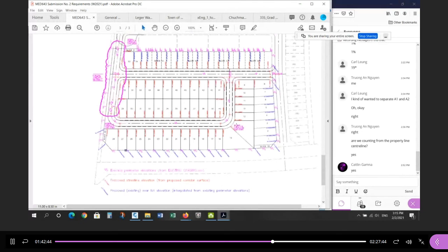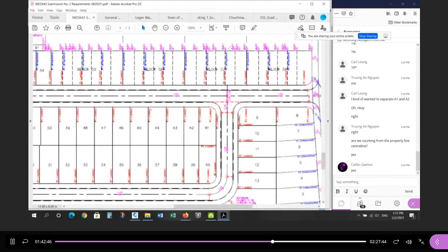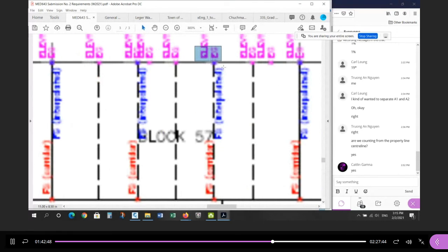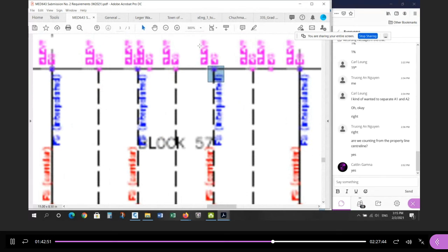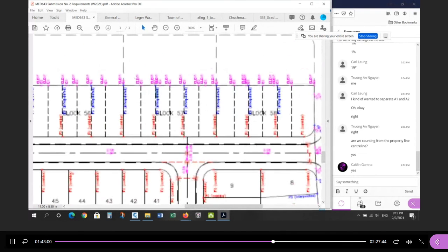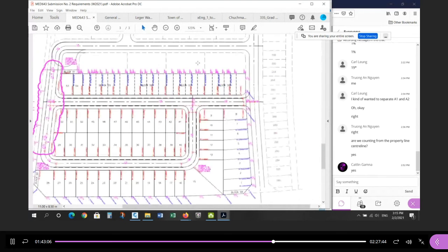around the perimeter. Now, again, there's some stuff that is going to be obvious. The existing point at the backyard here is exactly where you need it to be. So you just need to make a copy of this point. The proposed is equal to the existing. So it turns out that all the lot corners from these units and these units line up. Okay? So everything in blue is interpolated.